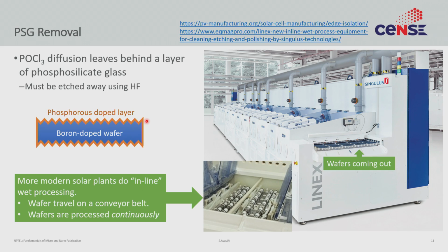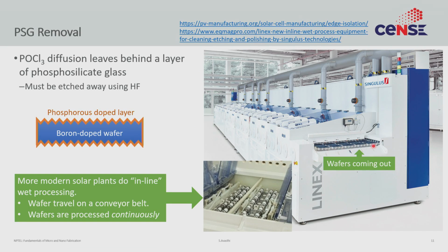So the wafers enter the assembly line on the back of this equipment, and internally it has these rollers, and the liquid is filled to the brim of these rollers. So as the wafer goes over these rollers, it touches the liquid underneath, and all the etching or whatever processing you're trying to do happens, and then you see the wafers come out on this. So it's like a belt process. It's like a conveyor belt.